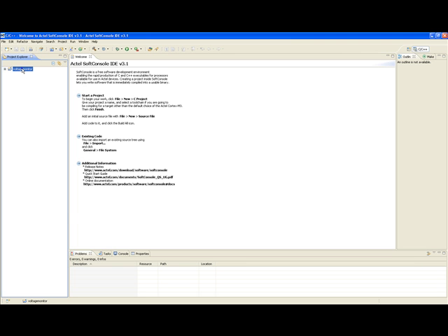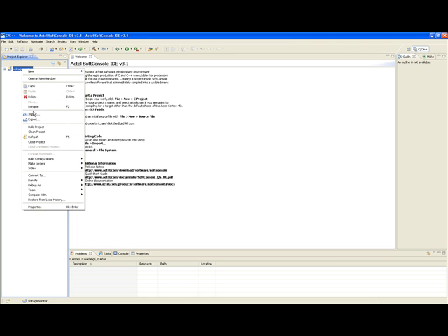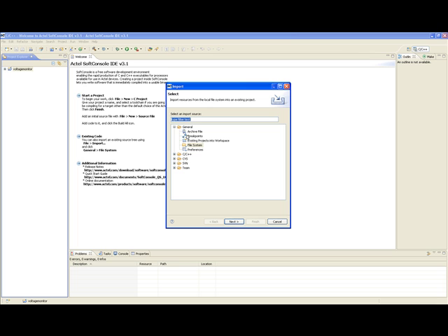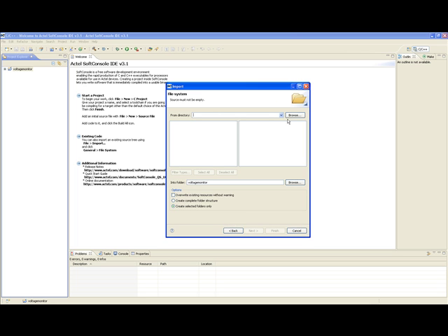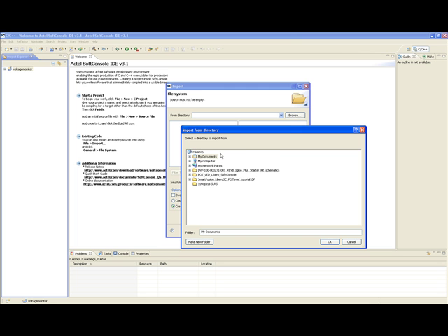Right-click the project name in the Project Explorer and select Import. Expand the General tab, select the file system, and click Next. Browse to the location of the SmartFusion Voltage Monitor project folder created from the Libero IDE. Open the folder, click the Firmware folder, and click OK.